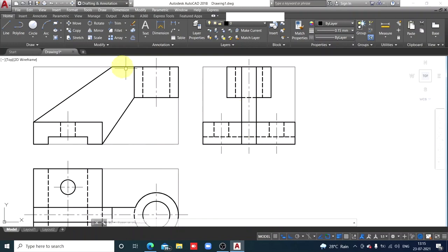So actually, listen. The visible portion of the plate is up to top of the base plate. So this portion up to the top of the base plate is visible, but the remaining portion of the plate is hidden behind this base plate. So this vertical plate is also present behind the base plate. If you check from left side, this base plate is closer to the observer and this vertical plate is behind the base plate.